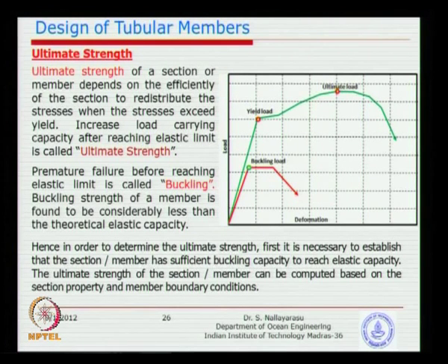So basically that is what we need to see, that premature failure by buckling is not a very good idea. We need to make the sizes sufficient enough that we never govern the design by buckling. We could say that, but sometimes we do that because of constraints. Many times you will not be freely allowed to go and make the sizes bigger.